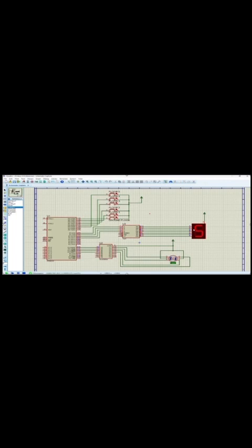After that, U2, the ULN2003, is a motor driver. The IC is used to interface the microcontroller with the elevator motor. It sends a signal that rotates the motor up or down based on the current and target floor. That allows the microcontroller to control higher current loads, like the motor, through a relay driver. And the motor symbol M1 shows rotation direction based on the signal.